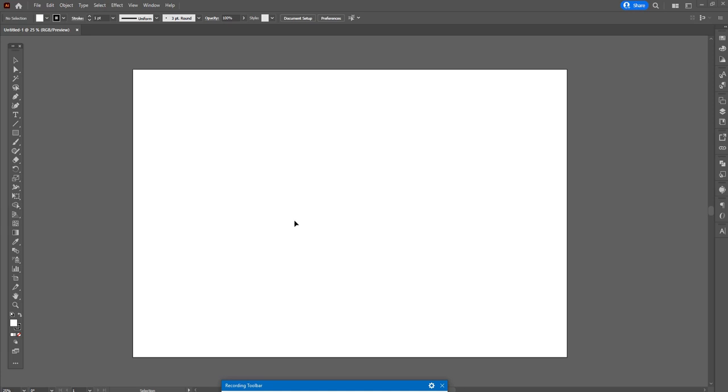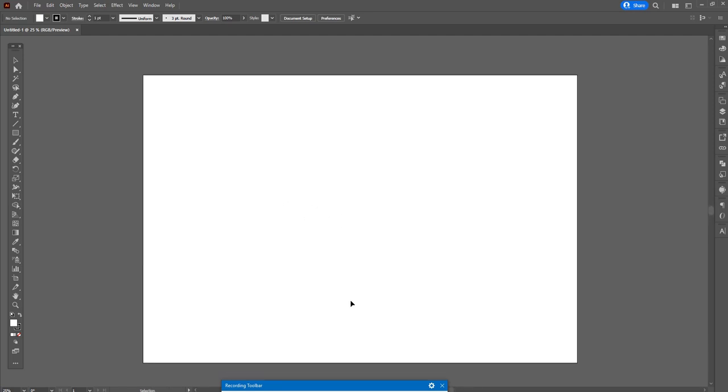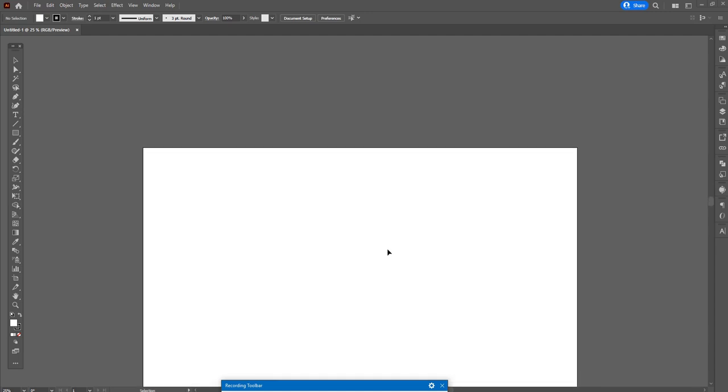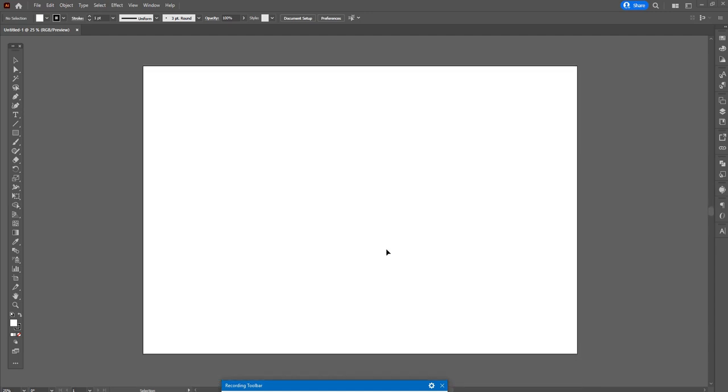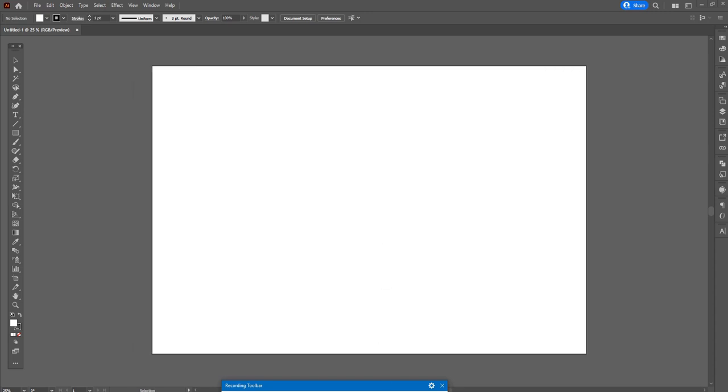So as you can see, now we're into our document. Once you're in the document, you can pan around it by hitting spacebar, left click, and dragging with your left click held down. To pan up and down the page, simply use your middle scroll wheel to pan down and up. If you want to pan to the left and right, you still use your scroll wheel, but you hold Control down, and then you use your scroll wheel to pan left and right.